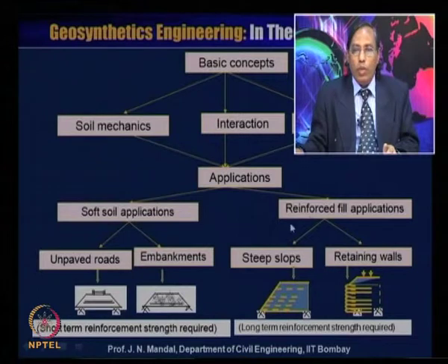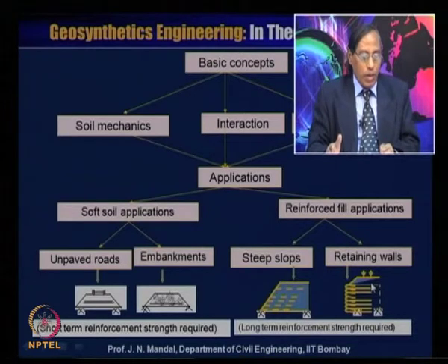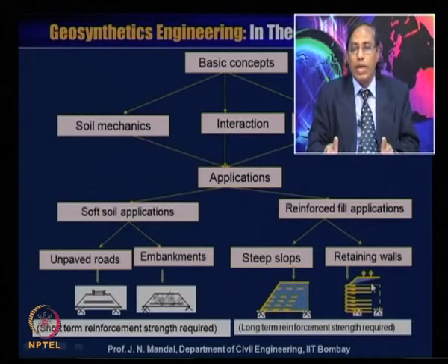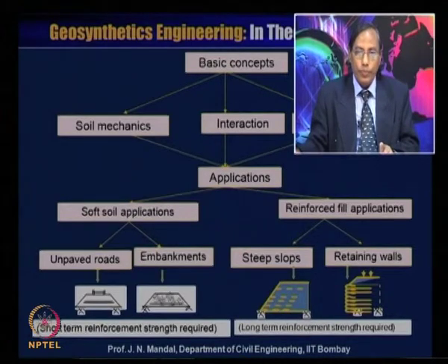Now, we will discuss the reinforced fill application in case of the retaining wall, reinforced soil retaining wall. And this requires long term reinforcement strength, and its service lifetime is in excess of 75 to 100 years.